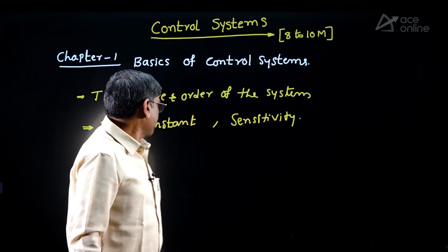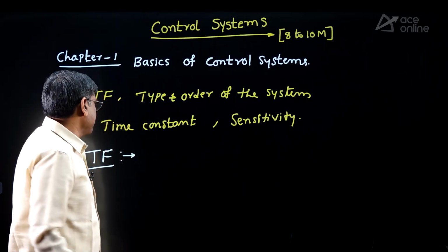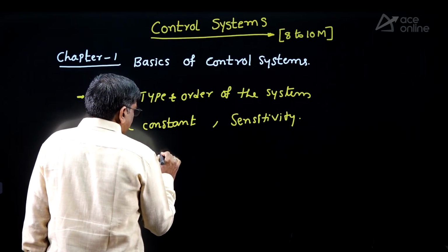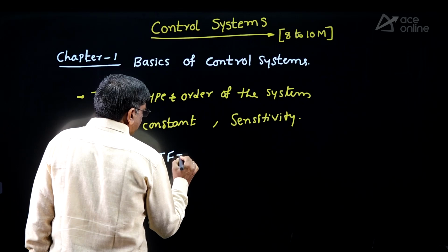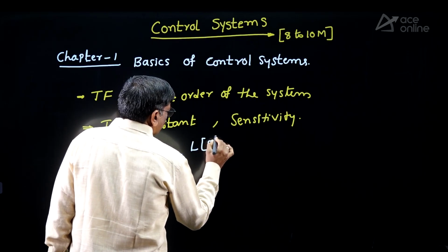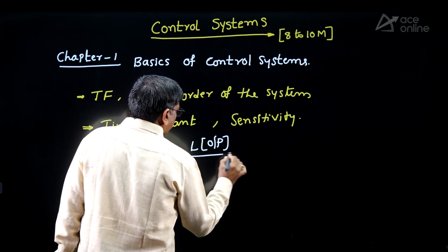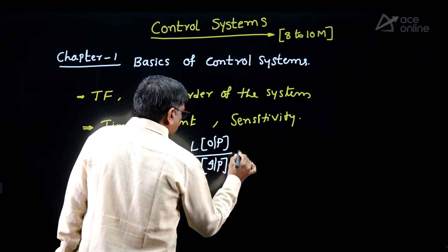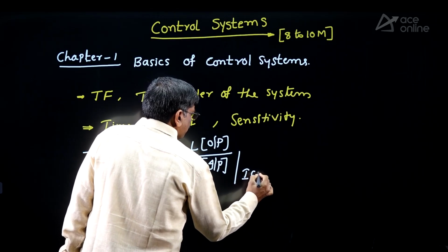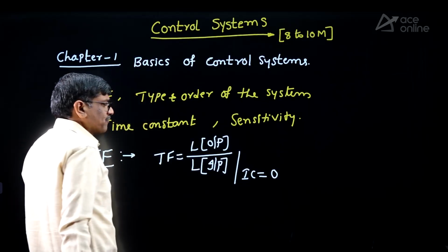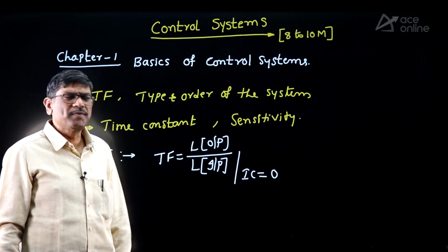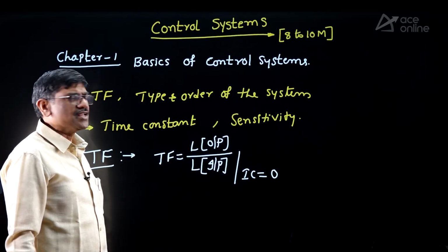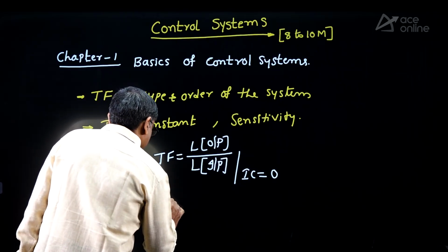The definition of the transfer function, 2 definitions are there. Try to write before me, take a pen and write it before me. Don't wait until I write on the board. Transfer function equals Laplace of output by Laplace of input with all initial conditions 0, one definition.